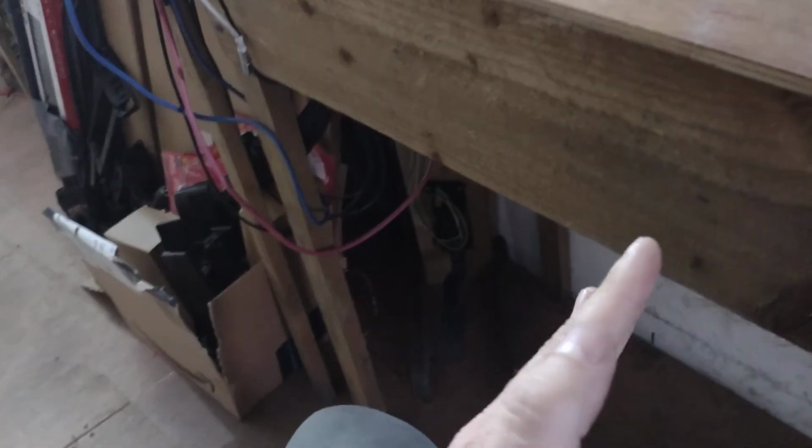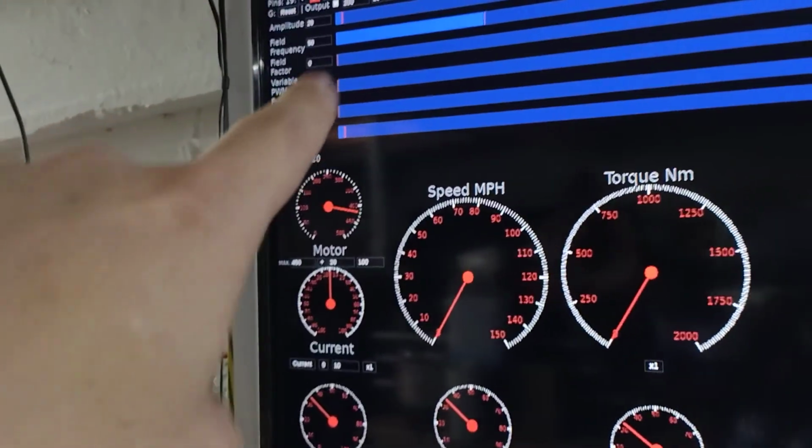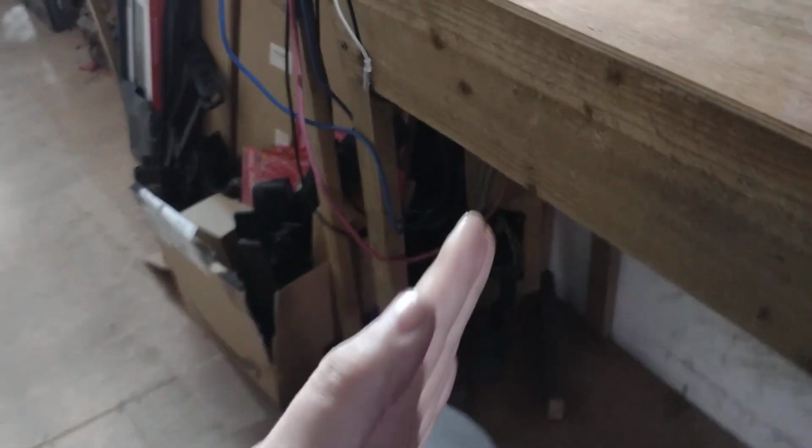So the net effect is, as you put your foot down on the pedal, first of all, it brings in the amplitude, which gives it the initial speed, right? It spins the stator because it's got a fixed frequency, and it brings up the amplitude of the stator, and then the rotor catches up, with a certain amount of slip, and then the frequency changes to keep that slip within certain bounds. And so effectively, the pedal works as it should.